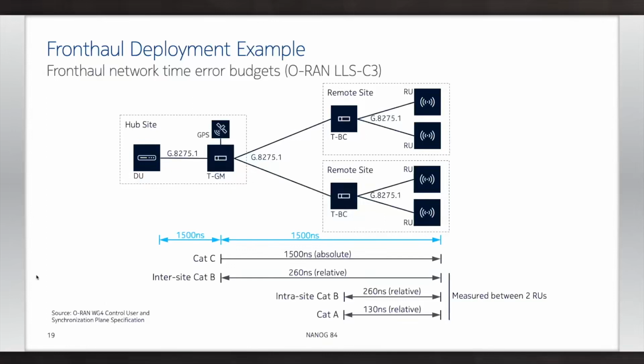So this means that you need to be concerned with the synchronization between any given two RUs and from the RU to the time reference. So if you have to choose a location to put your time reference, that probably should be closer to the RUs than to the DUs. The DU is a lot looser, not so strict in its synchronization requirements.